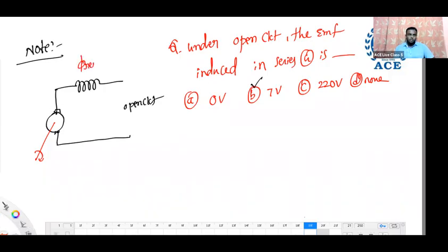Even if there is no field current, residual flux is there. So due to that residual flux, if you place a voltmeter, it will show some EMF EG1, because whenever you rotate, a small amount of EMF will be induced. That EMF is independent of field current. It is a small voltage, maybe 5, 6, 7 or 10 volts, anything.